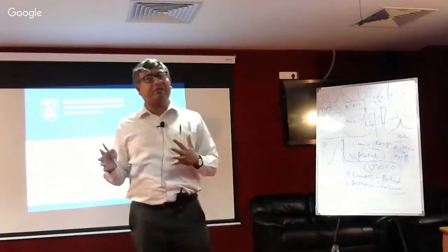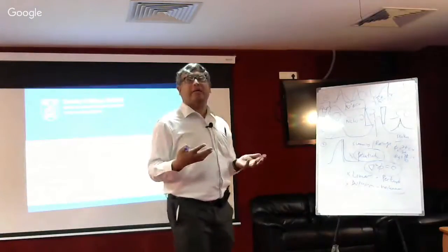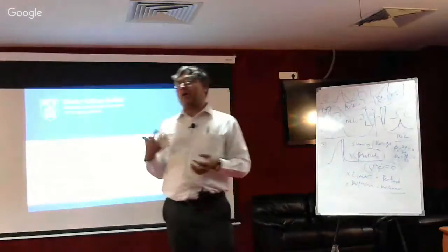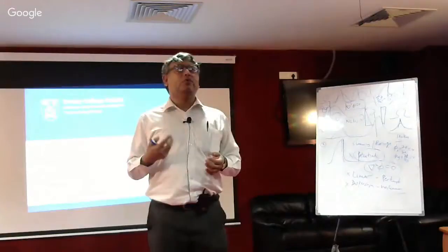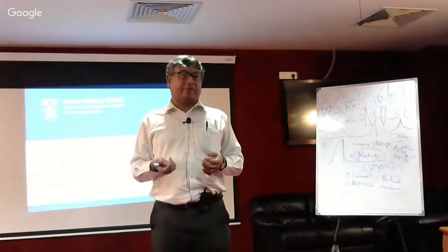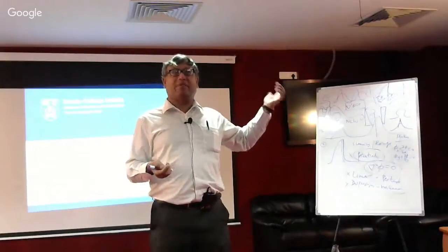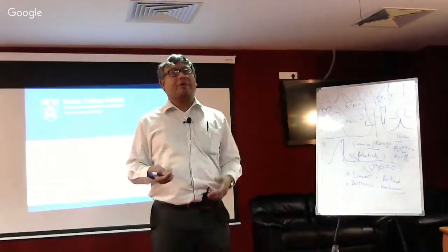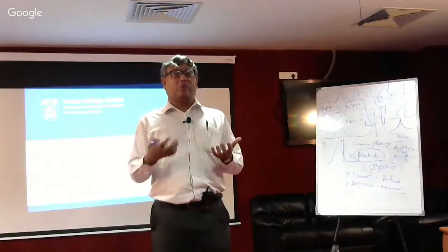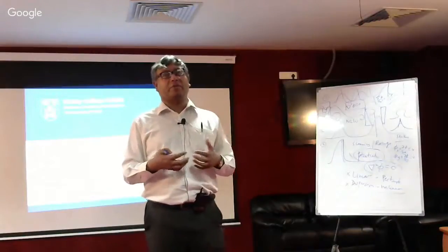Now, this theory is also something not fully developed or known, and all we do in analysis is use some empirical spectrum. As I mentioned about the turbulent spectra in wind, you also have spectra for waves, like the JONSWAP spectra or the Pierson-Moskowitz spectra.